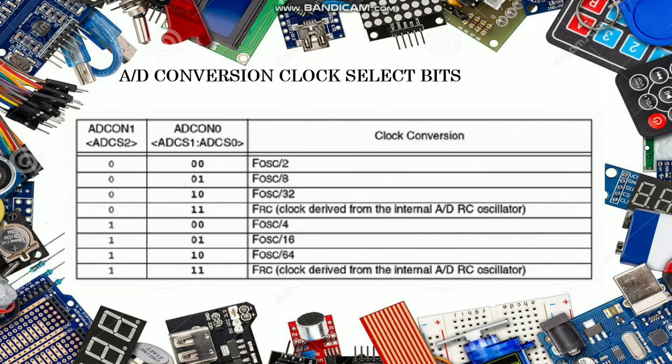So this table refers to the select clock configuration. You can see the binary number values which you can write to our ADCON1 and ADCON0 registers to get the respective clock conversion.